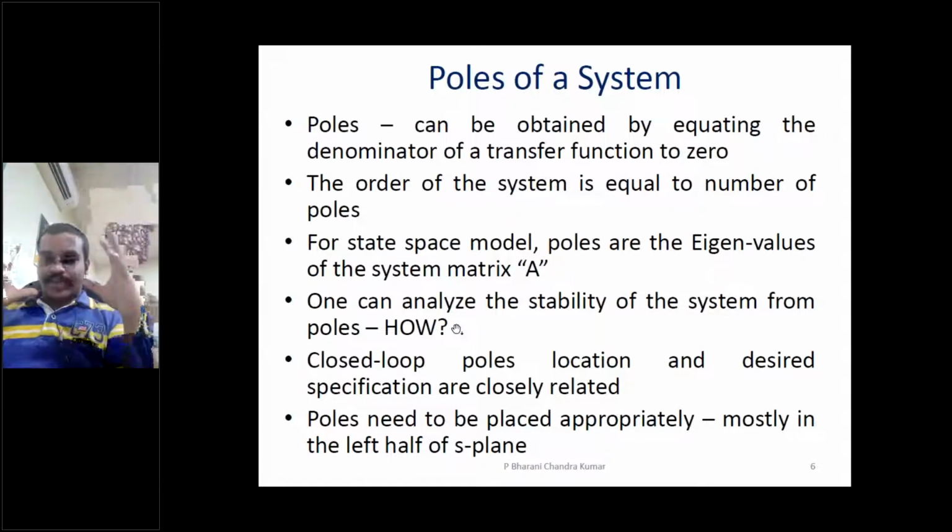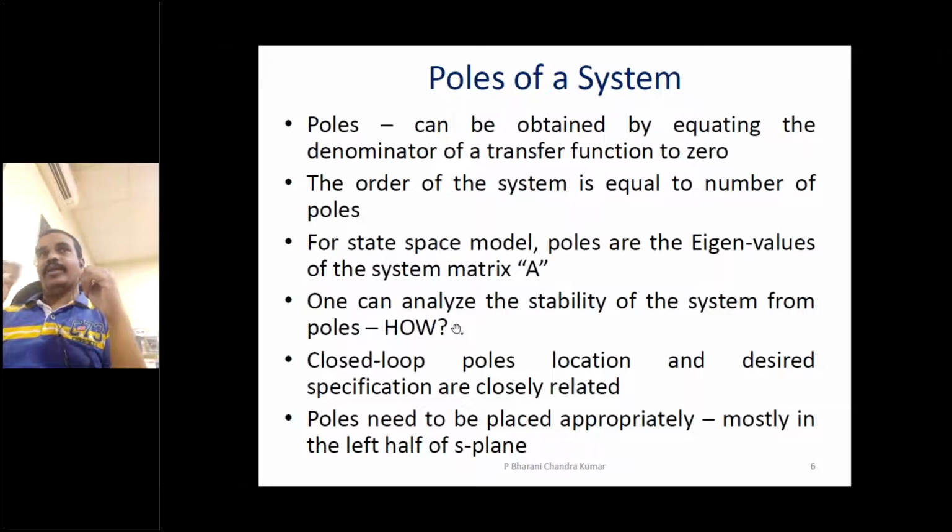If the bandwidth is very large, noise is a high frequency phenomenon, and the noise will enter into your system response. So that's why, as a control engineer, when you design any controller, not only do you have to focus on the time domain, at the same time you have to satisfy the frequency domain specifications as well. In this SDP, we are not going to go into much detail on the frequency domain, but just for the sake of practical concern, I'm going to tell you what the frequency response is and so on.